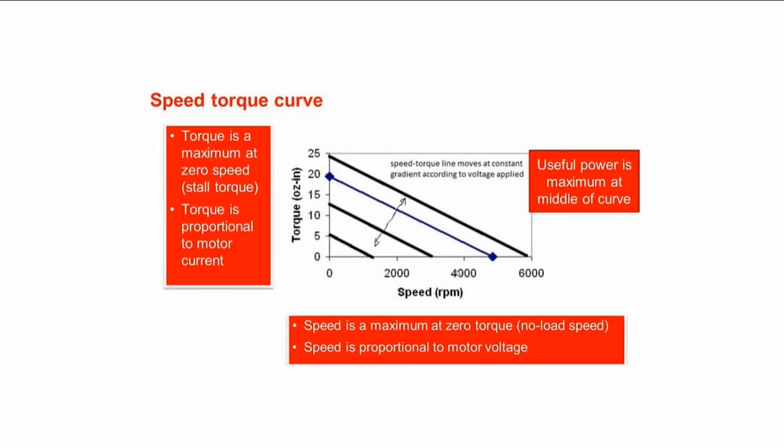The brush motor has very typical torque speed curves actually. It's very easy. You can see on your screen: as speed goes up, torque goes down. For example, in PMSM, in the synchronous machine, in the induction machine, the speed torque curve is very different from the DC machine.